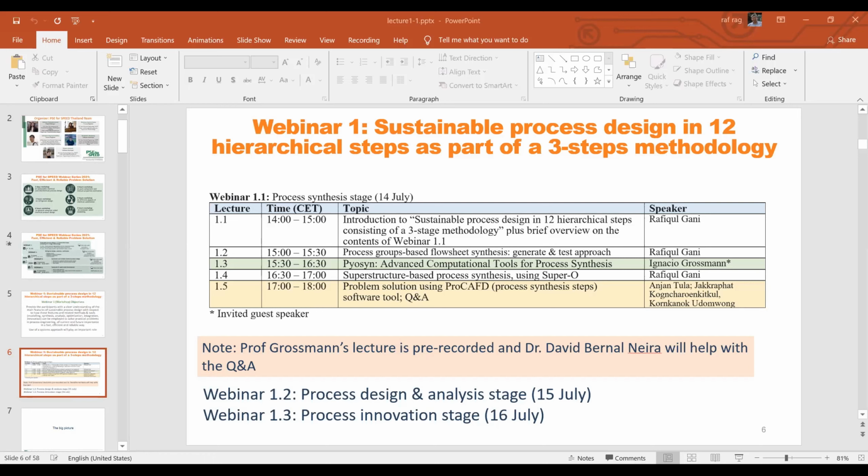So it comes afterwards, that after we have done the calculation for the binary ratio matrix, then we will do the azeotrope calculation. Because if the binary ratio says that distillation is possible, then we need to check whether they form an azeotrope or not. If they form an azeotrope, then it is not helpful if the ratio is high. But if the ratio is high and there is no azeotrope, then distillation is good. So I hope I answered your question.